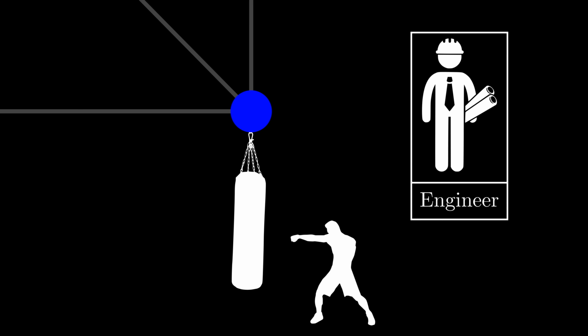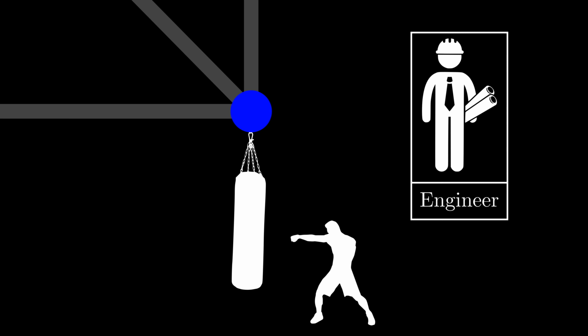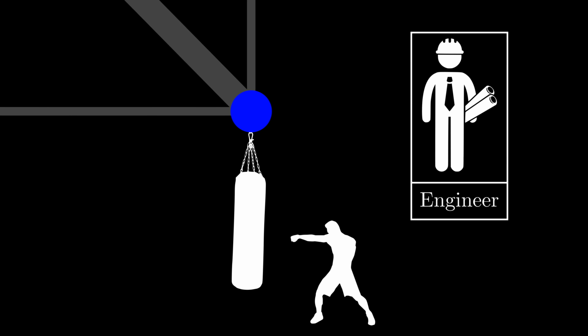For this purpose a ground structure is required, which describes which bars are available. Here for example 3 bars that are attached to the wall and the ceiling. One idea now for example would be to distribute the available material evenly across all these 3 bars. Or another possibility would be to remove some material from the bars on the left and on the right and to add this material to the bar in the middle. Alternatively, you could also distribute the total volume evenly among the bar on the left and the bar in the middle.